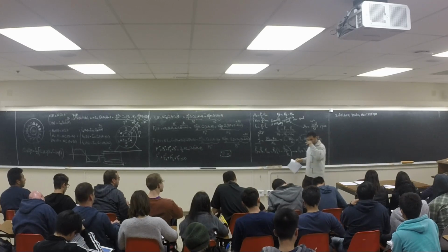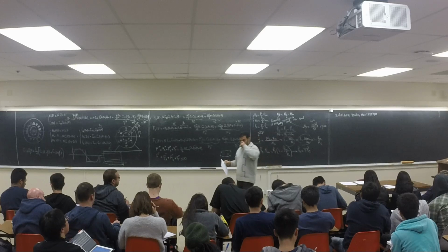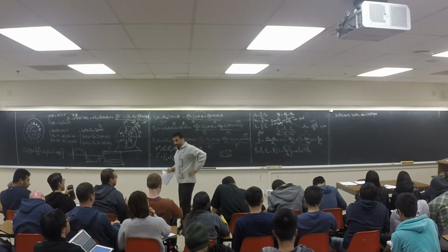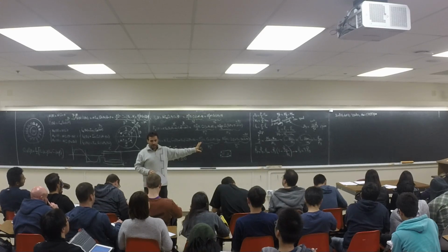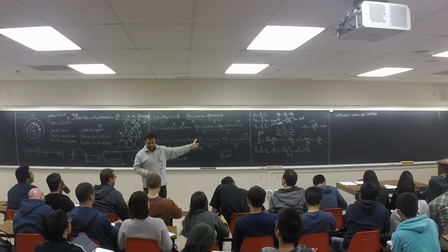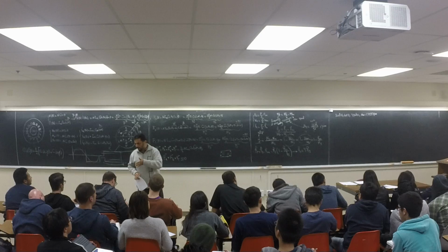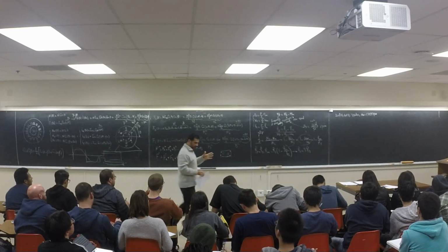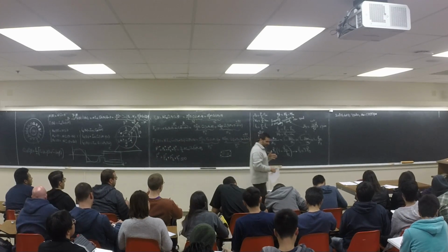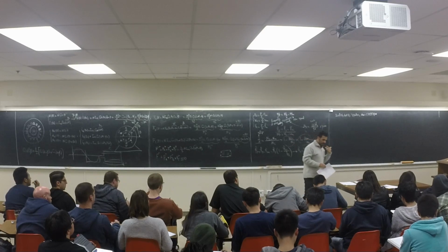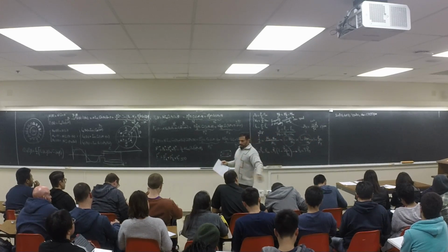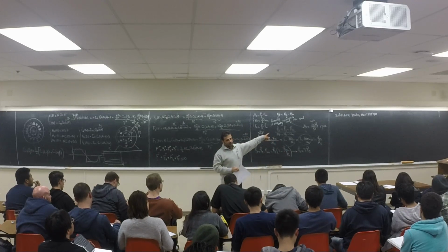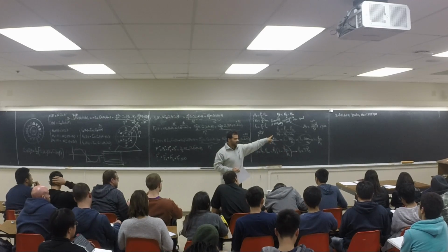So we have a machine. The rated voltage of this machine is 208. What does it mean? 208 volt, 60 hertz. We can connect this system to a 3-phase supply. For an induction machine, we don't say 3-phase; by default it's there. If it's a single-phase induction machine, they usually mention that. If they don't mention it, by default it's a 3-phase machine. So basically, we can connect this machine to a 3-phase, 208 volt, 60 hertz supply.